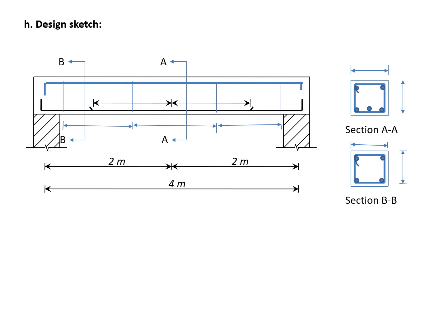You have to give B and D. Stirrup spacing will be different in sections A and B. Then you remember this for development length, distance you have to mention. You have to mention where it is curtailed. You have to show the span. And this has to be as neat as possible, because I must say that the examiner first looks at the sketch and then he looks at whatever else you have written. So it's worth 40 marks. Practice this very well. Thank you.